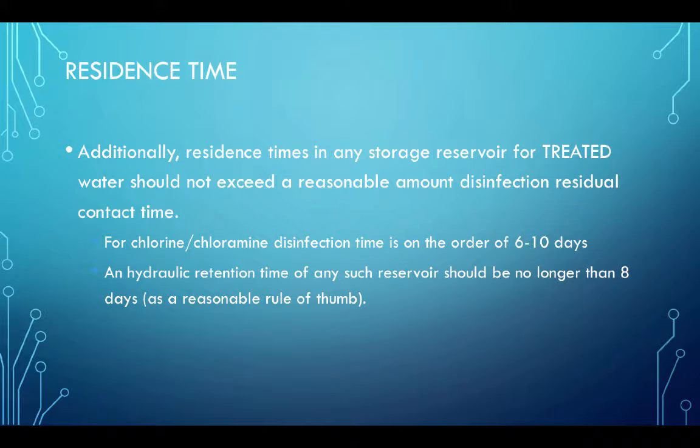As a reasonable rule of thumb, 8 days is probably workable. That's a little bit more than a week. Anything longer than that, you would have to consider that water is raw again, and then it would need another treatment process.